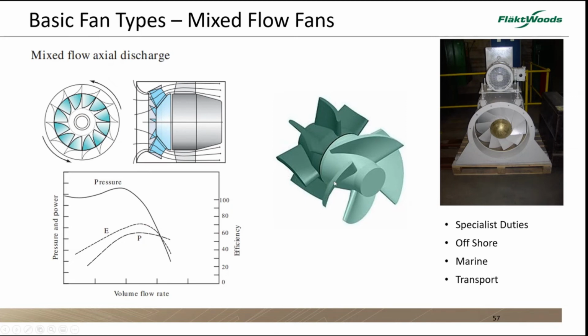But this shows the arrangement really, where you have an impeller that then feeds the air into a guide vane arrangement. Efficiencies are okay, but they do suffer now. This fan that was originally made then would not be acceptable in terms of ERP as a fan alone. It would be as a specialised fan arrangement, but not for ERP.